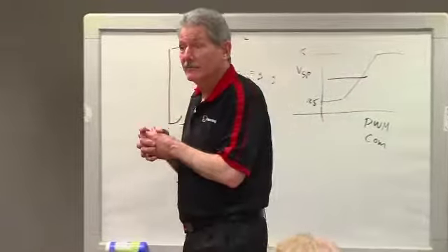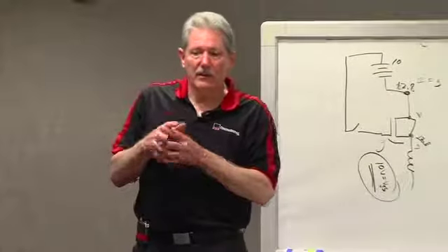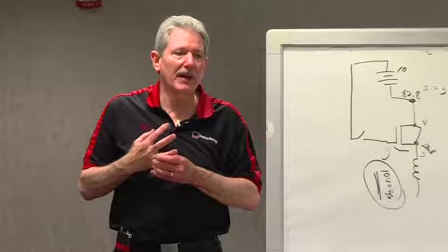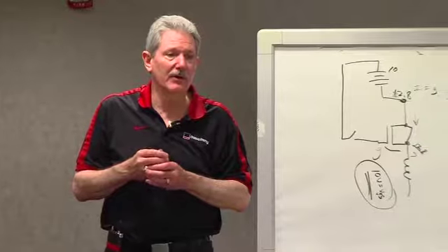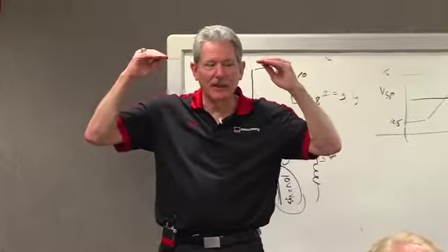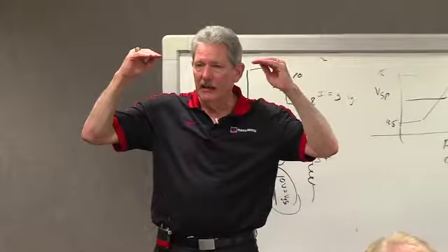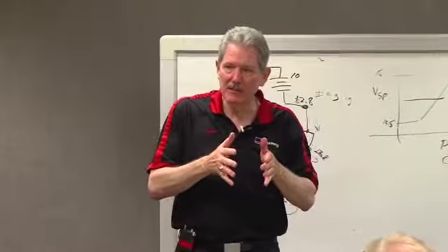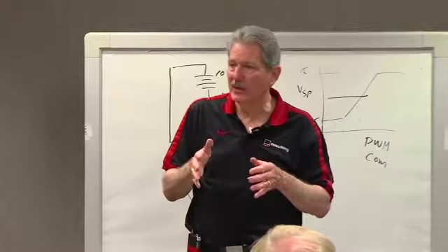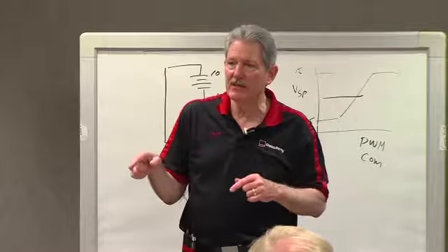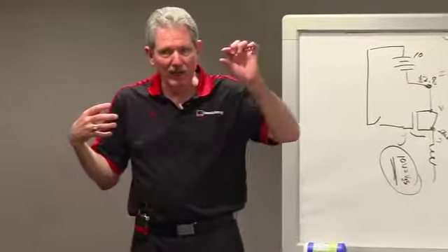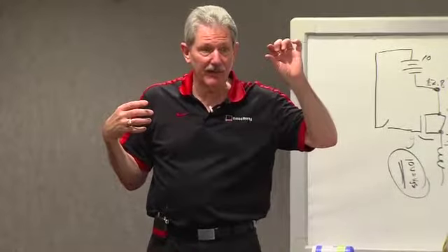Okay, let's talk thermal shutdown. We take cooling air from the airstream at about 125 or 130 degrees C. Junction temperature in our regulators can only go up to 175. At 175, the plastic pieces start expanding super fast. It's called the glass transition temperature. You don't ever want to operate above 175. But with the heat that's coming in, we don't have much margin between 130 and 175.